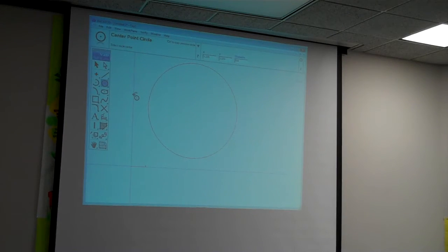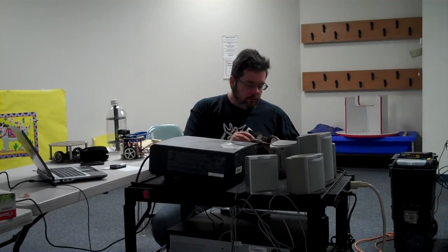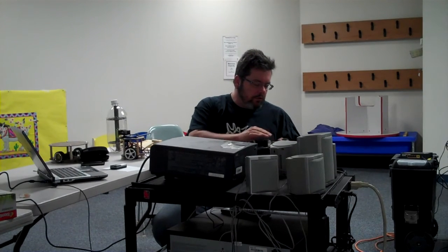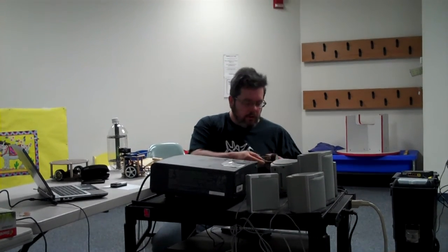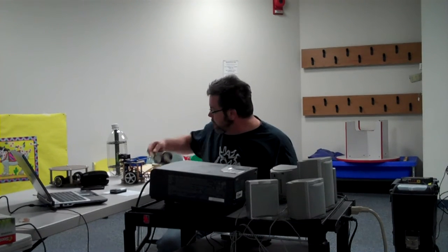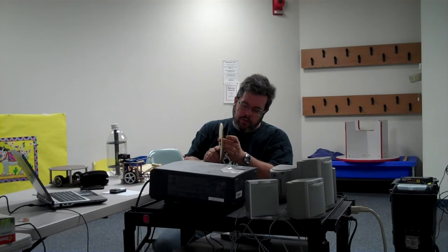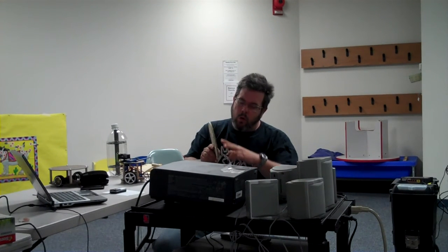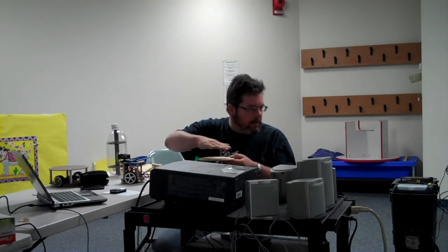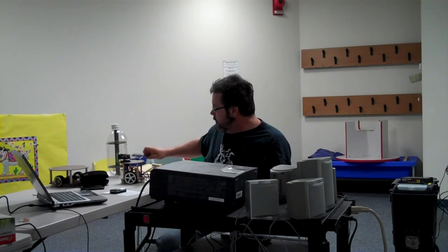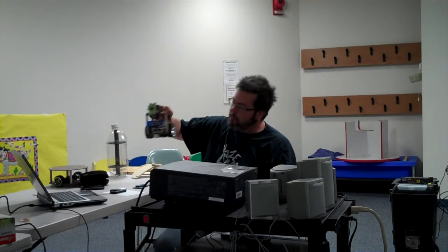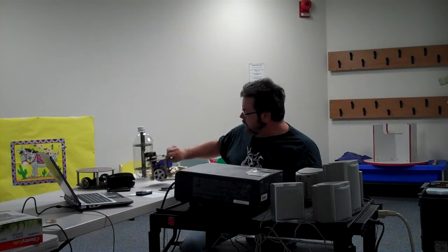They're not the best motors. They're real noisy, they're real inefficient, but they work. So you've got forward and reverse control over 2 motors independently. So it's nice for a little round platform. If we have something like this, we've got to get the measurements correct for the Tamiya gearbox, and also the mounting holes, and then also the holes to mount the other deck, if that's what you were doing. Similar to this robot, which has an upper deck with some supports. So we got to measure all that out. That will actually go very quickly.